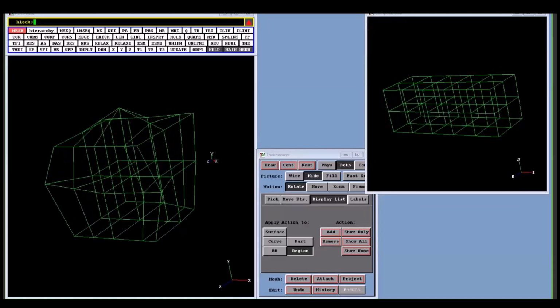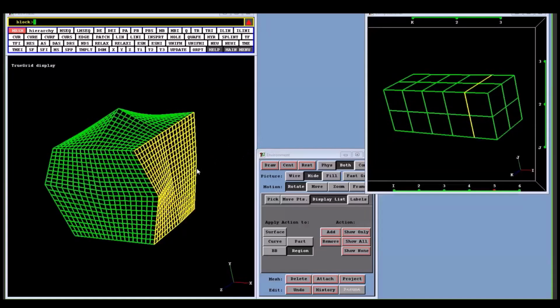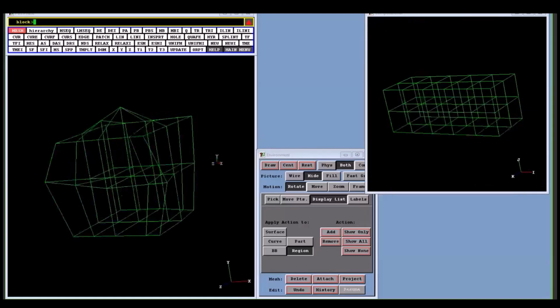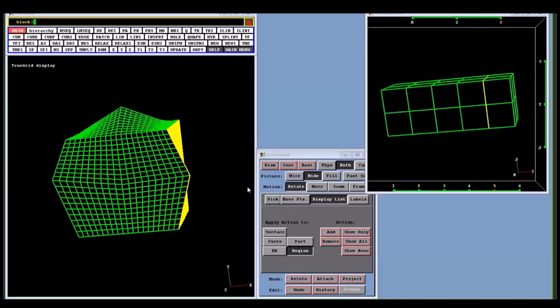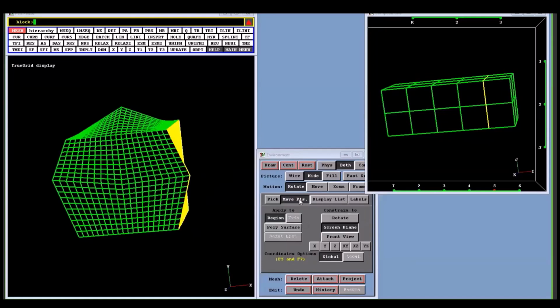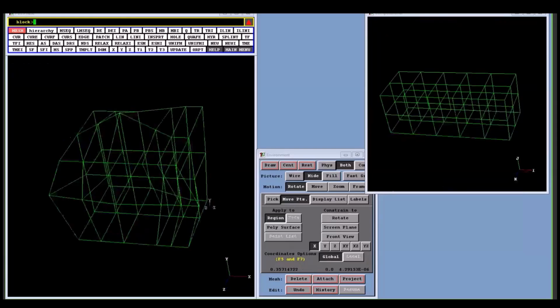If you don't have initial coordinates already assigned, then what do you use? So it's been collapsed down. Now what we can do here is move points. Let's select this face now. We're going to move this face, which is in the same location, as a rigid body, but only in the X direction. One way to do that is with the mouse: we click and drag, and it moves that face as a rigid body, and now we have thickness.